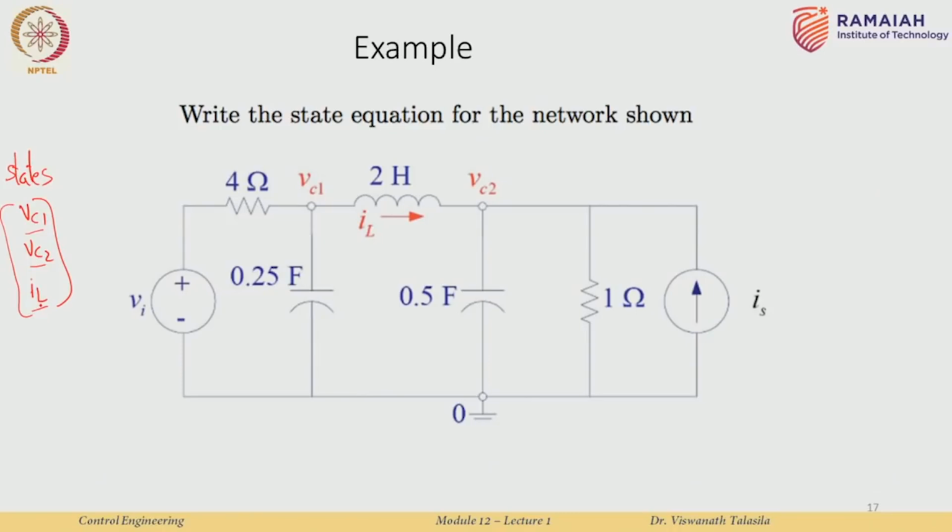Okay. So, let us start off and we can analyze this circuit in 2 steps actually. So, the first step is to basically write down the nodal analysis at these 2 particular nodes. So, basically we are going to write the KCL at these 2, and in the second step we are going to apply KVL in this particular loop, alright. So, first let us look at node 1, okay, and we will write the Kirchhoff current law at node 1.